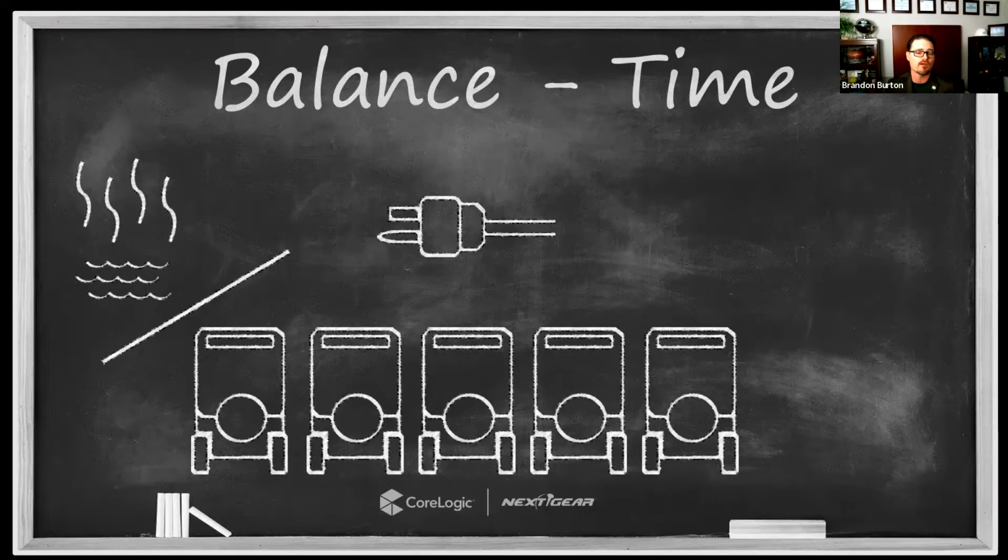Adding more dehumidifiers isn't going to fix that problem. It's going to exacerbate that problem, right? It's going to make it worse, right? How would I know if that's the problem? I would know if that's the problem by tracking my hour meters, right? I should see an additional 24 hours on that meter if I'm checking every 24 hours, for example, right? So let's say that that's not the problem.